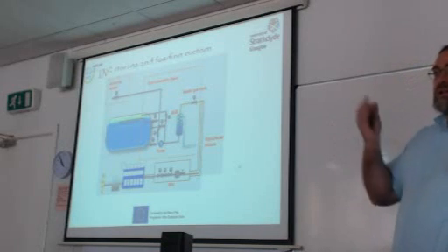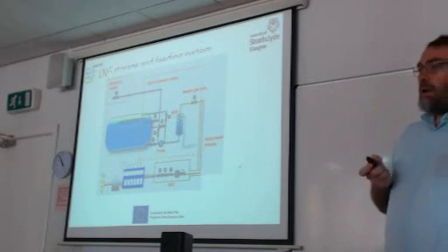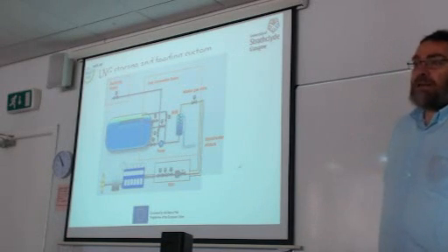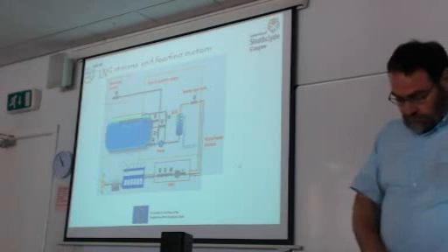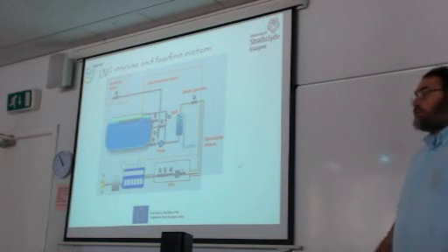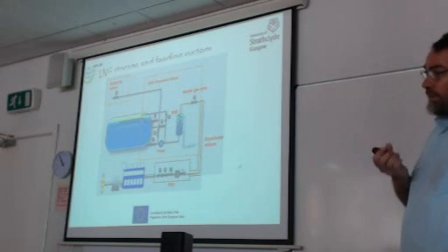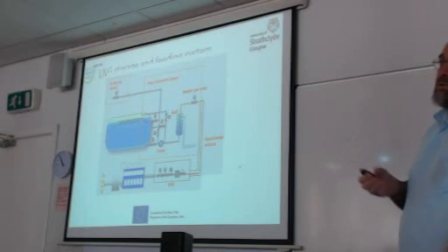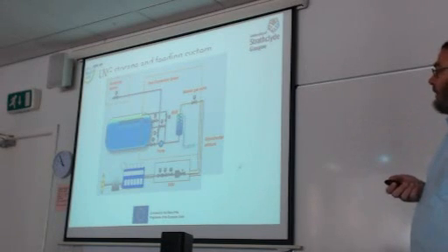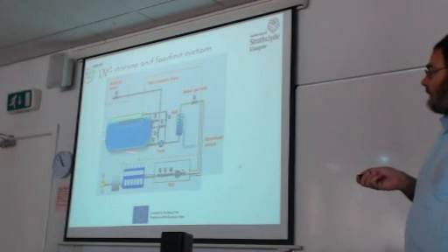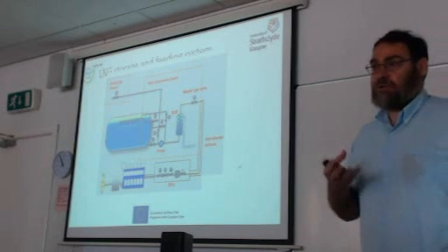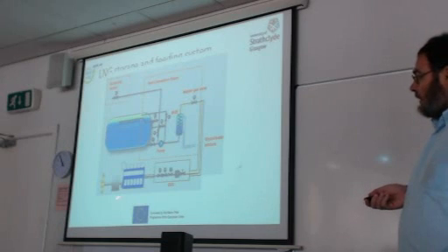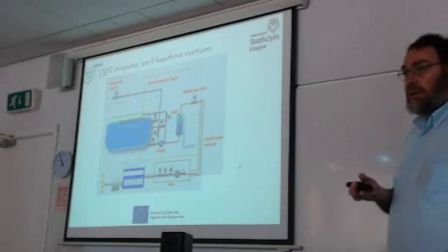Now we have the selection issue between LNG and compressed gas. Why is LNG preferred? Why is liquefied natural gas preferred instead of compressed gas? We could use compressed gas to avoid the very low temperature of minus 163 degrees Celsius. I think you must have covered this part in other lectures. So why is LNG preferred? Because of its higher density, so we need less space to store it. Exactly. So in this case, LNG provides the benefit of limited storage space required,